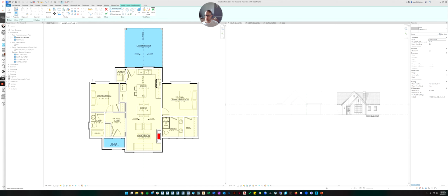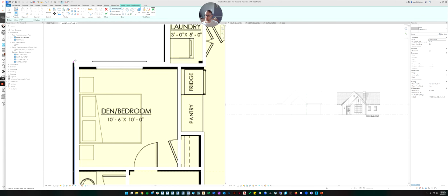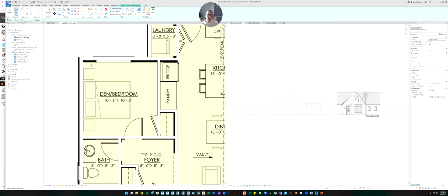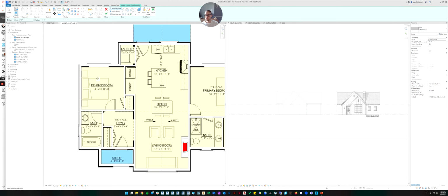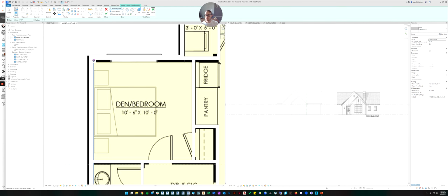Now we're in a sketch, and we just need to draw the sketch. It's up to you where you want the edge of the floor to be. Technically, we're not going to do foundations on this house, but you can easily do foundations if you want. All they are is a wall that's concrete. So if you want to draw a concrete wall underneath this wall, you can do that. We're not going to do that in this exercise. But if you were to do that, then the floor would technically sit on top of the foundations. But I'll probably draw the floor to the outside of the wall.